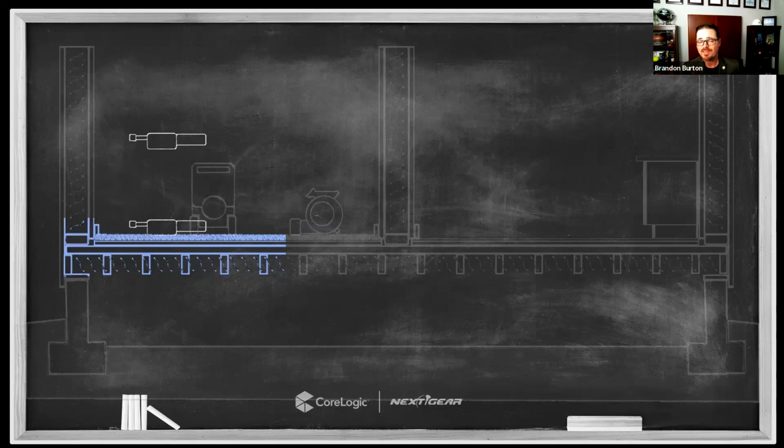The common mistake that a lot of us make is when we walk into an environment with a thermal hygrometer and measure temperatures and relative humidities, we're usually walking around and measuring up here at chest height, right? Which is an important measurement, but that's not the air that's doing the work. The air that is several feet above the floor or away from the wet surface is not what's drying the surface. What's drying that surface is the air in contact with that surface.